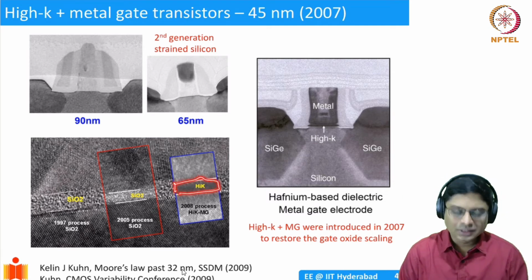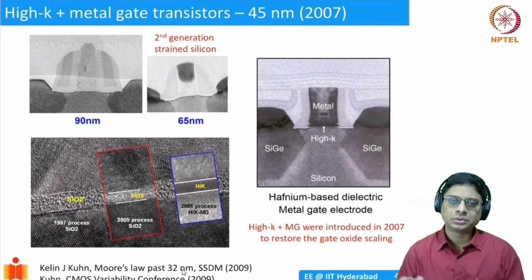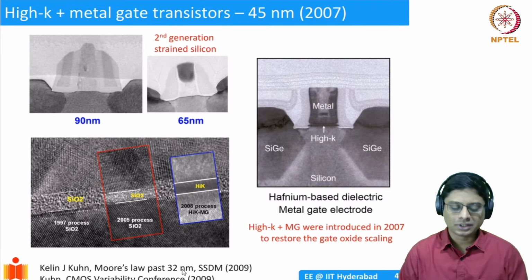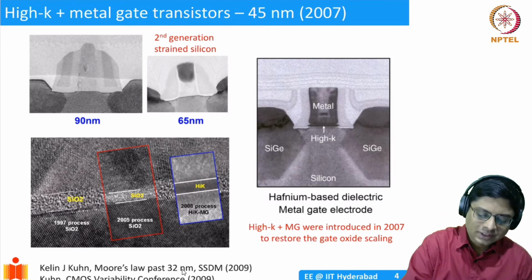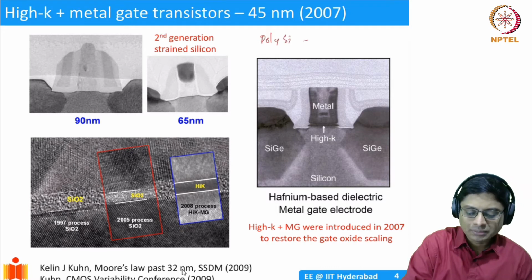They introduced this high K oxide. But then, if you introduce a high K dielectric, it was not enough to just introduce high K, because there were a lot of other electrical issues, and because of that, even the gate had to be replaced. So before 2007, the gate was polysilicon, but in 2007 it became metal gate. Okay, they had to replace both dielectric and the gate.